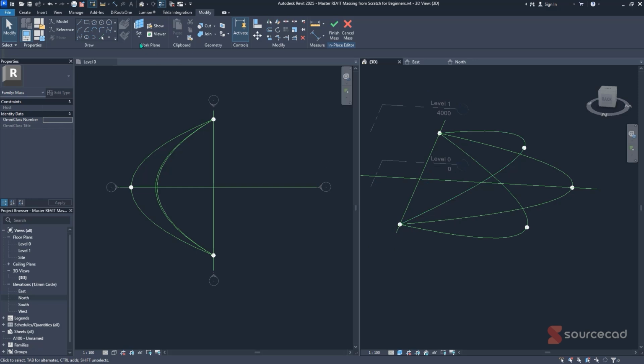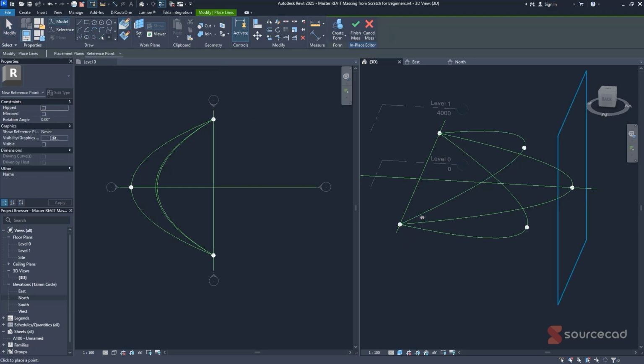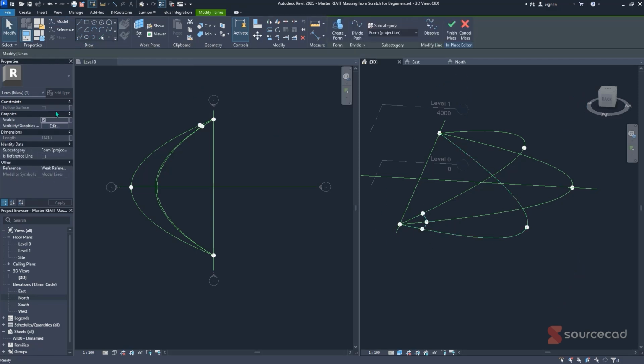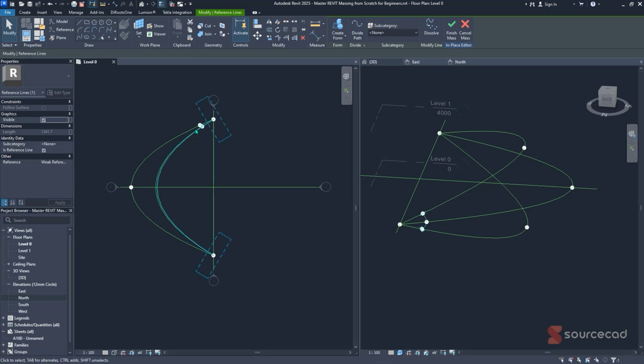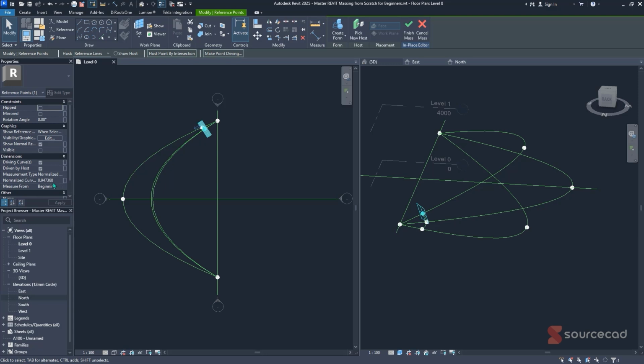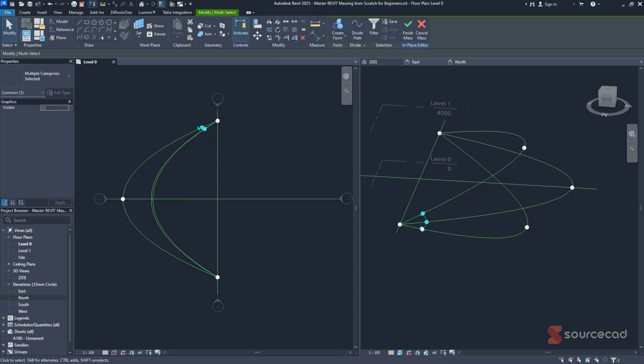And for us to add more control points, we can use the same point element. So I'll select the first and the third here, and then the last one here. Then I'll open my selection window, use the same command here, making sure that it's a reference line. After that, it's a matter of selecting these lines, and I can change my normalized curvature parameter over here to a value of 0.19 or something of the sort. If I move it within here, we can clearly see that you can now adjust certain parameters that you want. But for this case, let's just go with 0.94 and make sure everything else is like that.